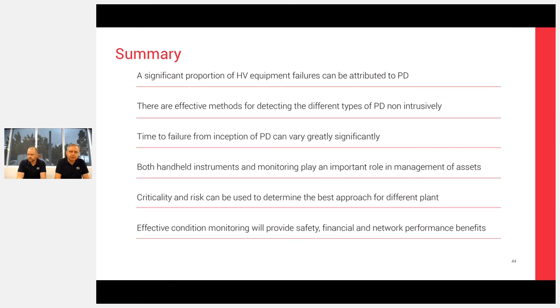Early stages of ultrasonic activity can be difficult to find at times. It will make a mark. With ultrasonic, it will be on the surface, so it will be affecting insulation. We often have to use strong light sources, mirrors, things like that, to make sure that we're assessing something. So the earlier you go in there, the quicker the fix, but at the same time, the less damage has been done to enable you to see it. So you do have that thing to think about.